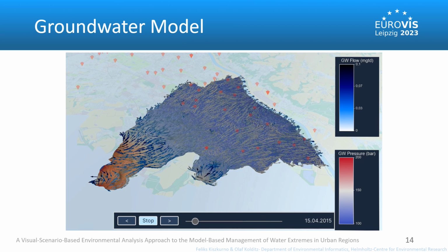For groundwater flow demonstration in the Lockwitzbach area, we used a simplified quasi-steady-state model in OpenGeoSys. The groundwater was driven by boundary conditions in the west and the river Elbe in the east, which are based on measured historical data. A part of the sewer network was included in the model in order to mimic infiltration and exfiltration scenarios depending on groundwater level fluctuations. The numerical simulation shows the temporal evolution of the groundwater surface and velocity distribution in the catchment during the simulated time period of almost 4 years.